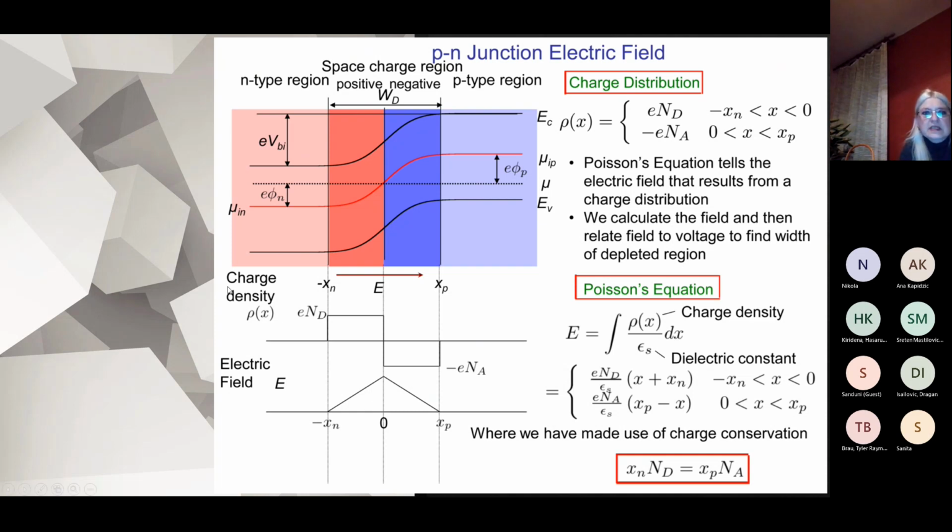And now, for instance, if we look at the charge density in this depletion zone, we just give some coordinates. If this point is 0, where the positive and negative charge are connected, then the end of this depletion zone will be negative, with coordinate -xn, and in the opposite direction the end of the depletion zone will be at coordinate xp.